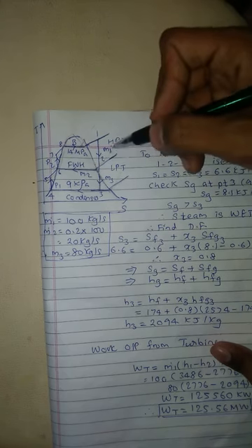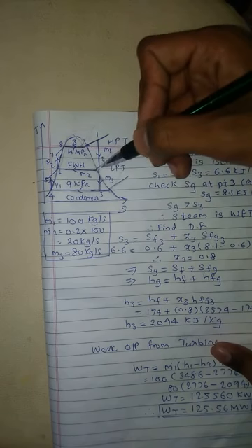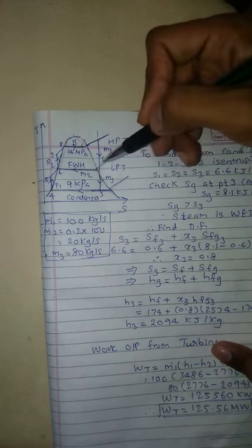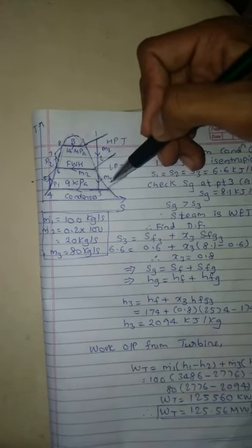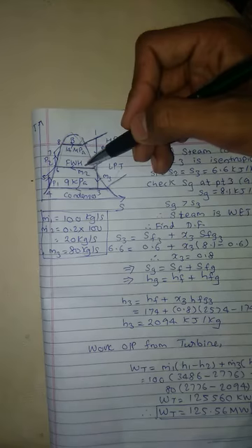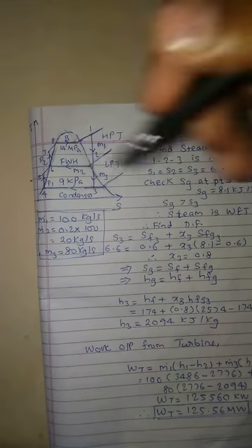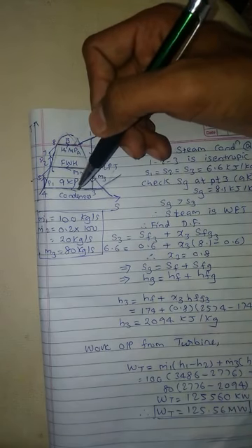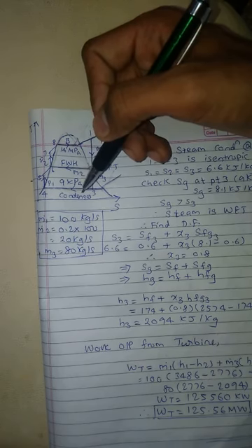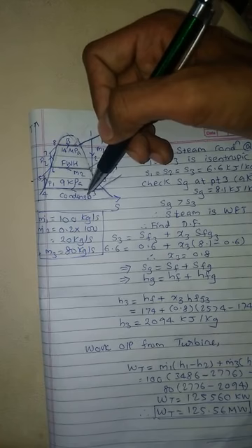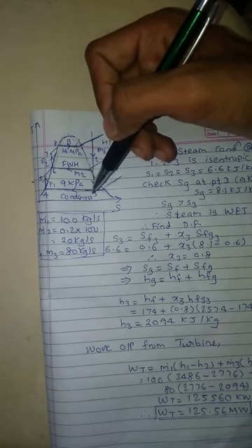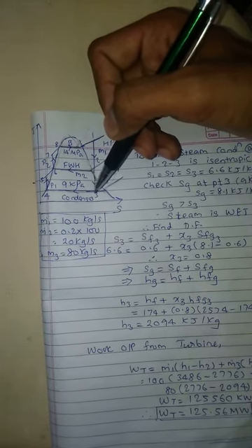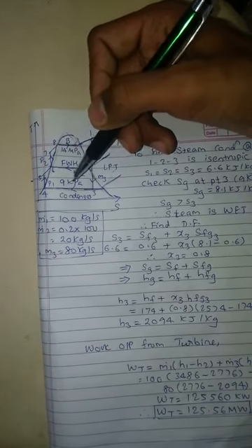M1 is the mass flow rate. After coming to this point, part of the steam goes to the feed water heater and the remainder goes to the LP turbine. Now what is this feed water heater? Basically the feed water heater is a heat exchanger consisting of tubes through which the feed water flows. The bled steam is passed over these tubes, where it condenses and transfers its latent heat of vaporization to the feed water flowing in the tubes.